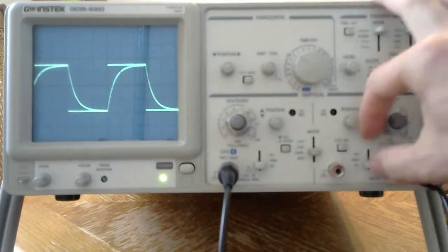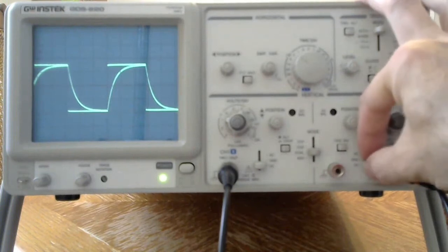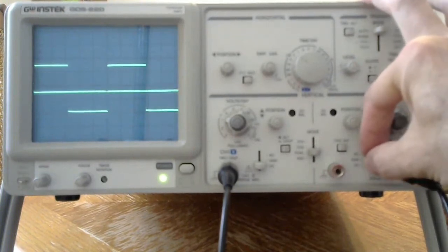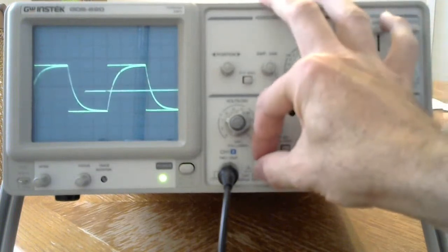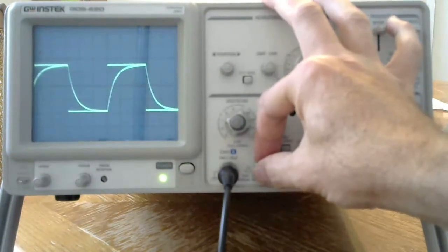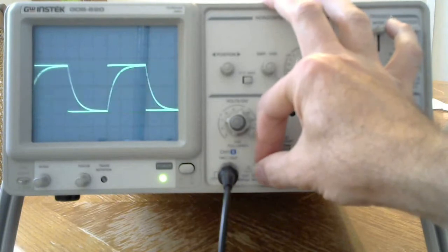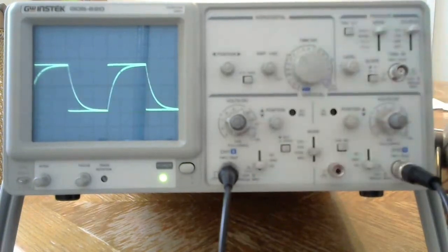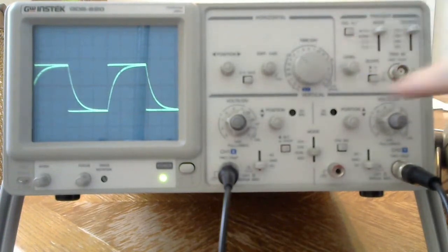Okay, and I can turn off just one of the signals by setting this lever here to ground. That basically turns off that input. Okay, and I can do the same thing here, turn off this input. Okay, you see that the square wave just becomes a straight line because it's at 0 now. Okay? All right. The final thing on this oscilloscope that you need to understand is this segment here.